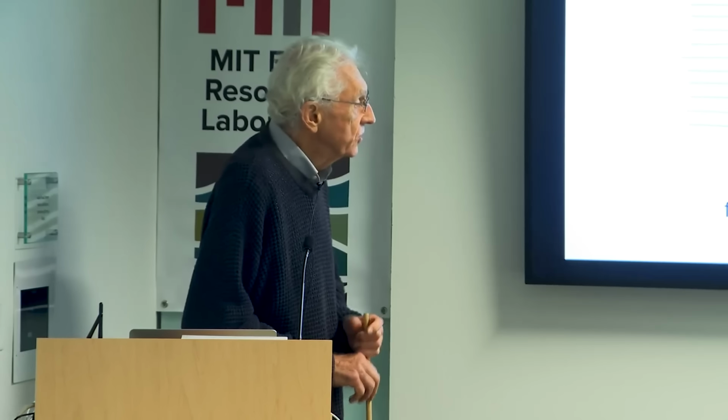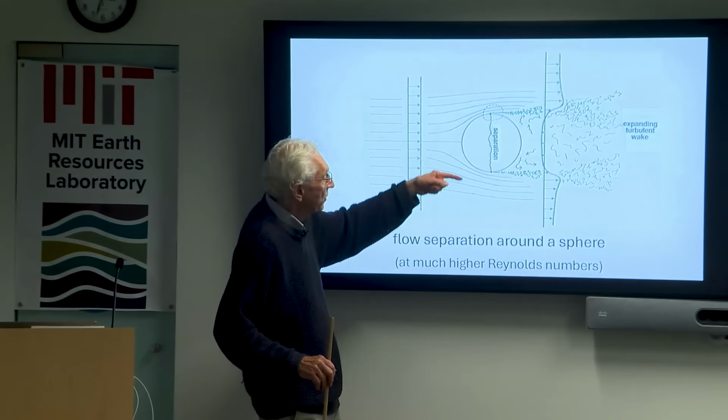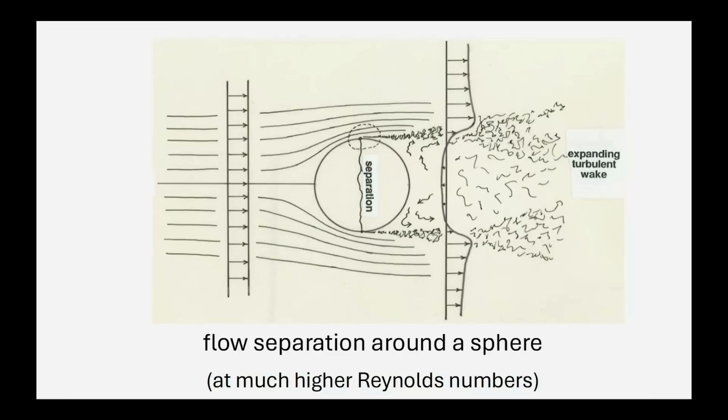But you have to live with that. So this is what it would look like around a sphere. Now this separation is not a line. It's a circle that goes around the flow transverse cross-section particle. And that's where flow separation, so there's a ring, a flow separation ring that goes downstream of the flow, with the kind of thing I described, a turbulent shear layer developing all around as in a disk, with this blobby mass wake right behind the sphere.